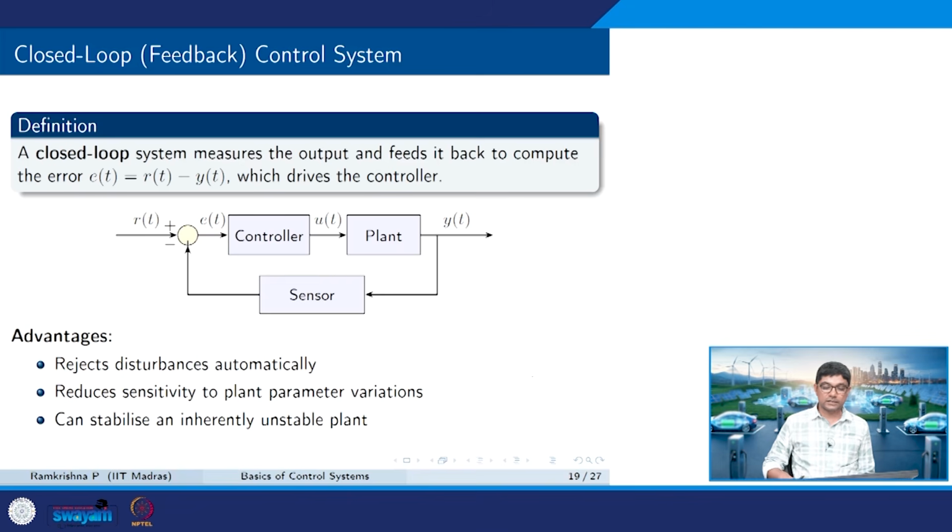Okay, closed loop system. Okay, I have a plant. There is a controller which gives a certain input to the plant. I have a Y which should match R, and then there is somebody sitting and just monitoring if Y and R are the same. Just like when I switch on the air conditioner, right? There is a temperature setting which glows, right? That is my reference. There is something which is measuring the temperature of the room and pumping in cold air as required. And when the room temperature is equal to the desired temperature, the control just switches off. It doesn't really need to put in any extra hot air or cold air.